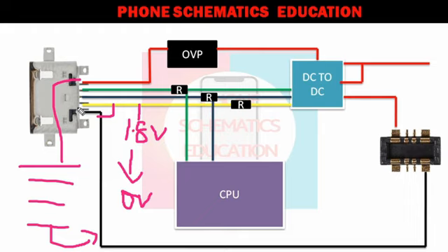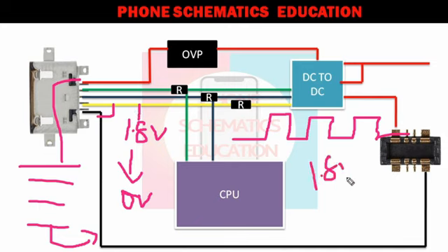Through this, when the 1.8 volt goes to ground, your IC, any IC, works on a binary language like 1010, right? So for the IC, first there is 1.8 volt, and now in this line 0 volt. How? Your pen drive has it. When your pen drive or OTG connects both these lines together, that's why your 1.8 volt connects to 0.